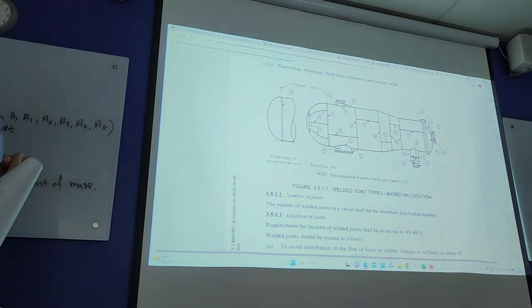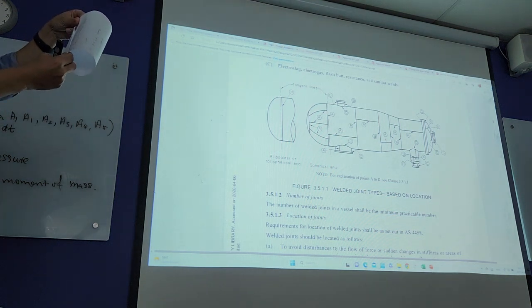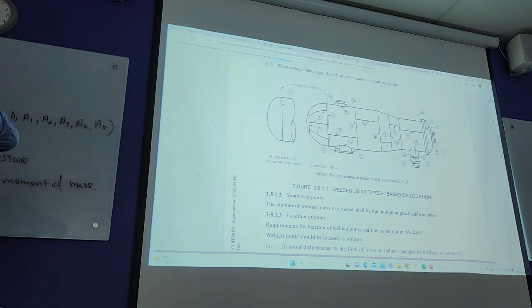Alright, because it depends on what type of sheet metal you use, right? Let's say this air vessel is actually long, the length is very long. One sheet metal is probably not enough, then you have 2 pieces to cut, and then you have to show that. Of course, if it is a single piece, easy, very nice. Just one line, right? If you have 2 sheet metals, you have to design such that the seams cannot be near each other.